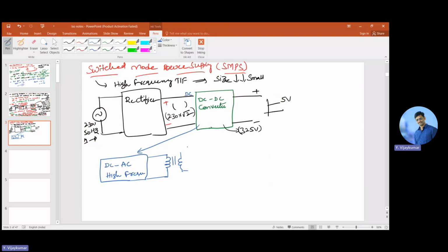So this high frequency transformer is drawn like this here. In this one, we are going to have 2 secondary windings, because we can take any number of secondary windings in the transformer secondary. Now the advantage with this one is I am able to take 5 volts from one winding of the secondary, and I can take the remaining voltage, 15 volts, here. So I can give this to a rectifier 1, and I'll give this to a rectifier 2.